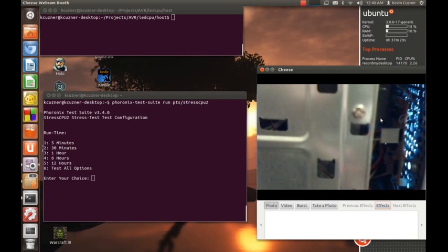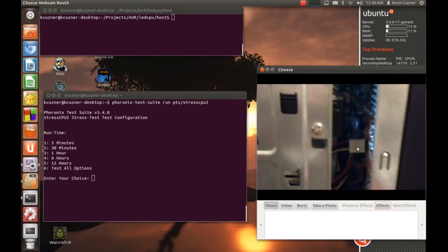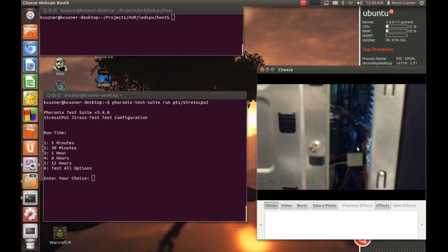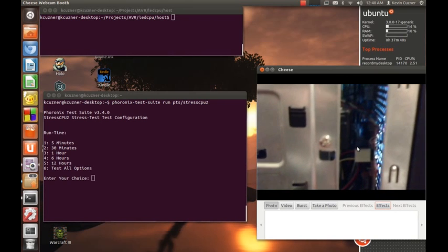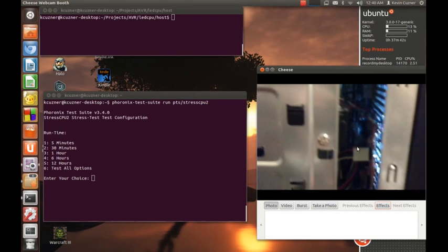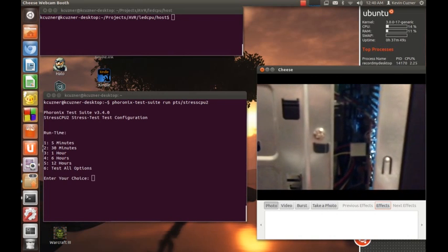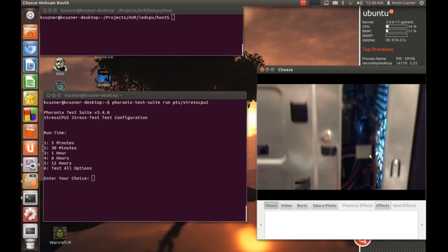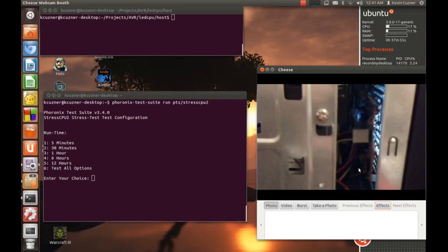You can see that I decided to make it not fully USB powered, because the USB buses stay active when the computer is in standby, and I keep this in my room and it could be pretty bright at night when my computer is on standby. So I have the Molex connector that's usually used for floppy disks connected up to this thing, and I have a programming header I installed.